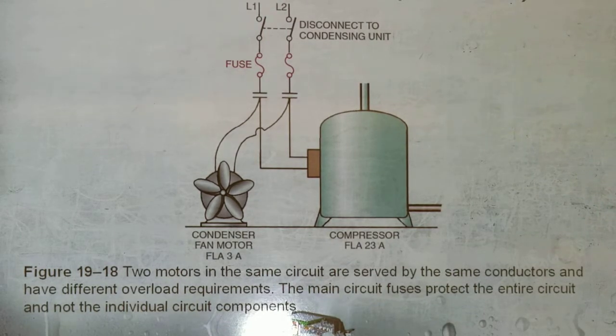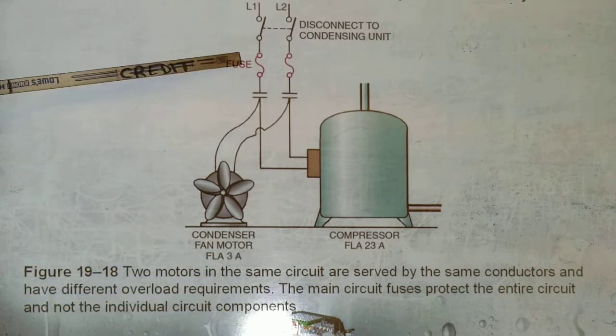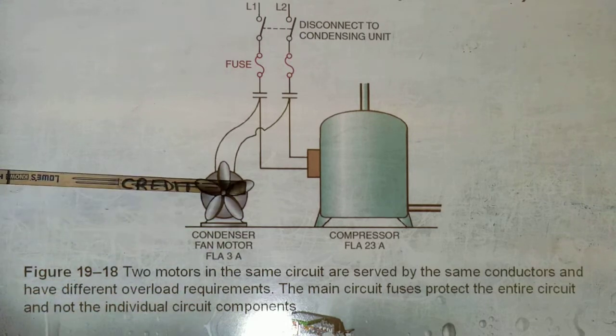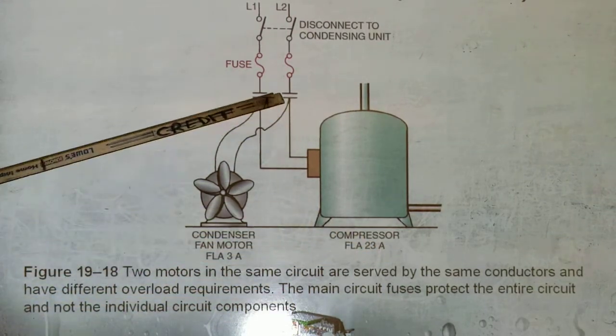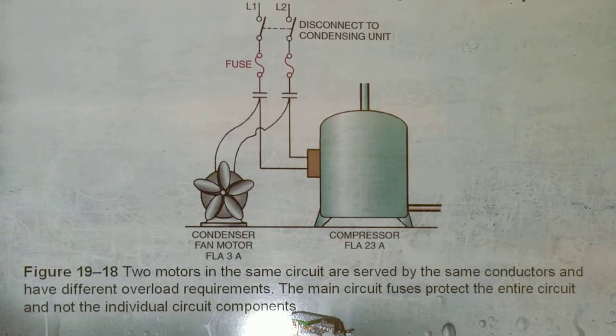Okay, so that's what those fuses are gonna be sized for. So it's not gonna be 23 amps, not gonna be 3 amps, it's gonna be about 30 amps probably. Okay? That's in the disconnect itself. It's the fuse disconnect. We have those, yeah, all of this here.